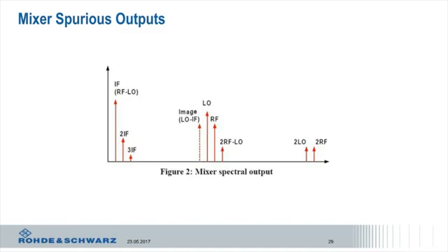So really, you're going to have to design filters around your signal to get rid of these things. But the challenge is to make sure you don't get a signal that pops up in your filter bandwidth, and that's really one of the challenging things in doing this. Again, you can find lots of spreadsheets and things that help you do this, but you need to be aware of it and figure out all the frequencies.